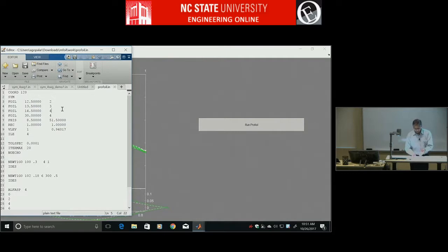Yeah, the rule is on the upper surface, increasing the alpha star will make the gradient more favorable. Decreasing it will make it more adverse. Okay, just go back and refer to it. And so we have to decrease the alpha stars. Let's decrease it by 1 degree and see what happens. Sometimes the change will be very small and you have to decrease it by more than that. So let me make it 2 and 3.